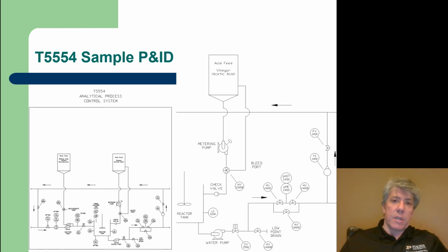So like I said, there's some interpretation, because a lot of times you'd expect that second letter to indicate a modifier of the first, but instead here pH goes together as the item being sensed. So PHE 1400 is a pH element, and PHIT is a pH indicating transmitter. Now, something you need to know about these sensors, these pH elements, is that they're kind of like batteries. They go bad after a certain amount of time, and you have to replace them.